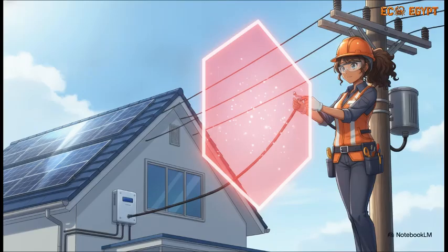Now, what happens if that grid suddenly just dies? Say there's a blackout. That's where anti-islanding protection instantly kicks in to stop exporting power. Think about it. If a neighborhood loses power, utility workers are sent out to fix dead wires. If your solar inverter just kept pumping out 400 volts into those supposedly dead lines, it would be absolutely lethal. So using active frequency drift and passive voltage monitoring, the inverter detects the outage and completely shuts down its output in milliseconds,